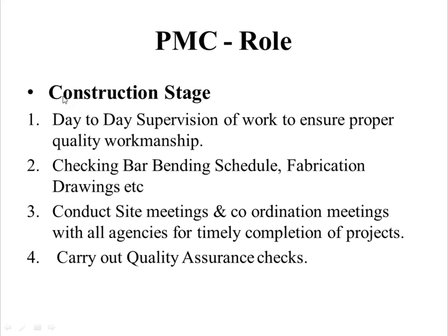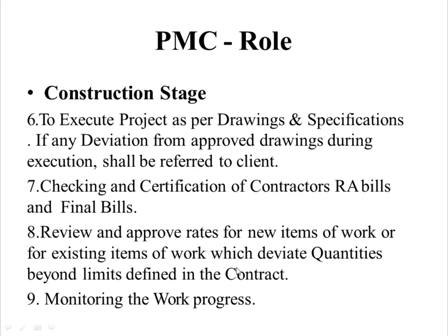Then the next role of PMC is during the construction stage or the execution stage, which is the most important. It is day-to-day supervision of work to ensure proper quality of workmanship, then checking bar bending schedule, fabrication drawings, etc. Conduct site meetings and coordination meetings with all agencies for timely completion of projects. Carry out quality assurance checks for the various materials. Then to execute a project as per drawings and specifications.